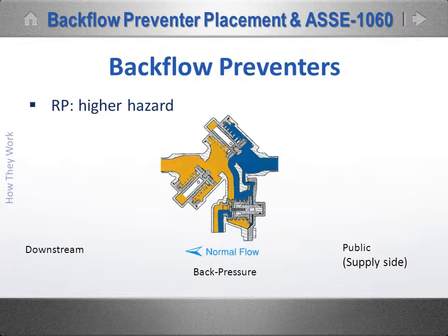Now, the main thing to take away from this is that both valves, the double check and the RPZ, perform the same function when they're operating properly. But only the RPZ is designed to use universal forces, specifically gravity and water pressure, to dispose of any backwards flowing water, even if the device fails. And by the way, they do fail.